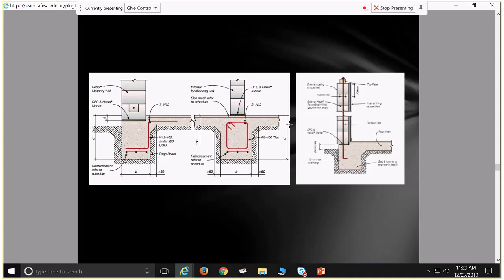So does everybody here in this room know what a Besser block is? Anybody who doesn't? Right, so Besser block's pretty ubiquitous. They're hollow in the middle. So you can set them, let's say you set them on a concrete slab like this. Before you go setting out, when you're pouring your slab, you cast in some steel reinforcing, those bars, at every 300 millimeters or 600 millimeters, always increments of 150 millimeters, because that's where the spacing of your holes in Besser blocks are. But you cast your bars in there, and then later on you put your blocks out and you can fill that with concrete.